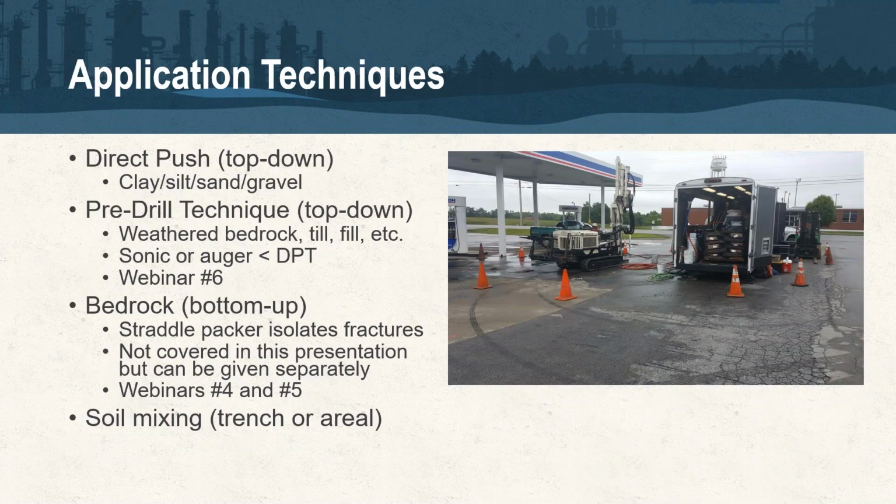All right, so I'm just going to spend one slide on application techniques. So direct push, I think it's best practice to always inject top down. That's probably a discussion, if you want to, again, reach out to me. I can dive into that a little deeper, but we think it's best practice to always use top down techniques. Really, for any injectate, I think it's really more important. It's critical for when you're injecting slurries in any of those geologies that I have listed.